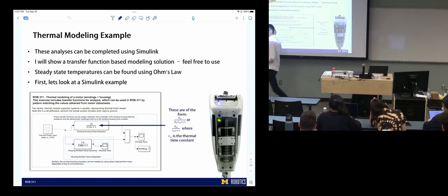Where did this come from and what does this represent? The movement of the motor. What? The output of the motor. So on, off, like it was walking. It was walking. Yeah, this was like a prosthetic. We were talking about this in the context of a knee prosthesis. We were speccing its behavior and doing steps. So we modeled that behavior as a time that it's on and a time that it's off, and then we just continued it forward in time for a long time to really see how its temperature changes.